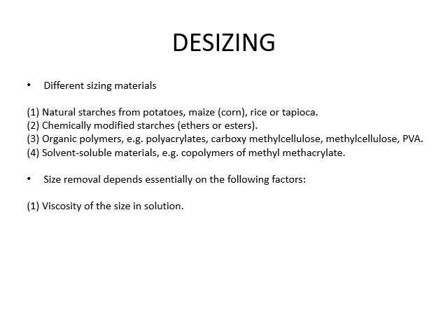But according to the required strength for the warp, the sizing viscosity matters more to strengthen the warp threads. So here viscosity is directly related to the penetration of the size material into the yarn. If penetration is higher, definitely the removal process will be lengthy.